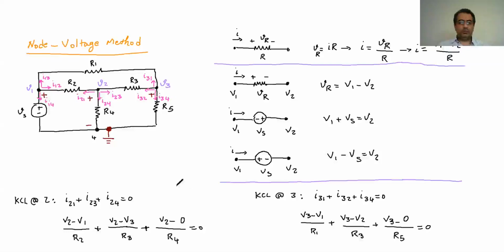This is the simple one for 2. I write it for 2 nodes, and then in the example, we'll see how we actually use them. For as many nodes as we have in our circuit, we write all these equations. At the end, we are going to have multiple equations and multiple unknowns, and then we solve them simultaneously to find all the unknowns.